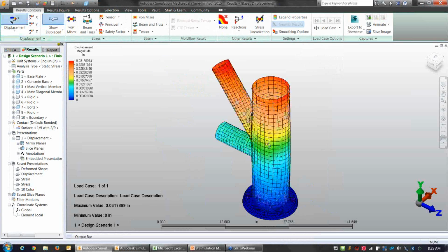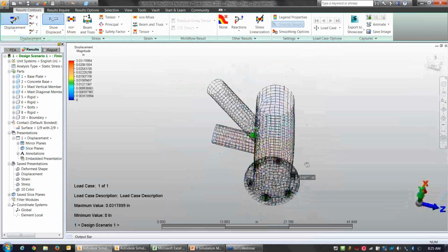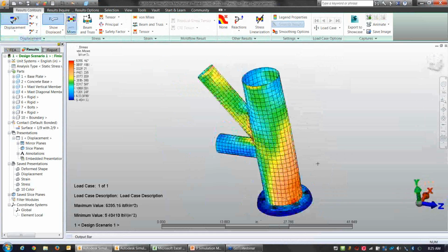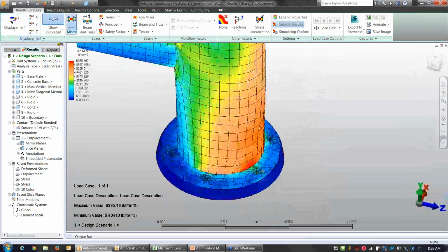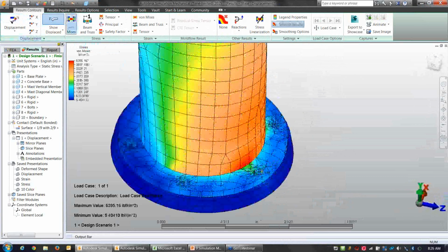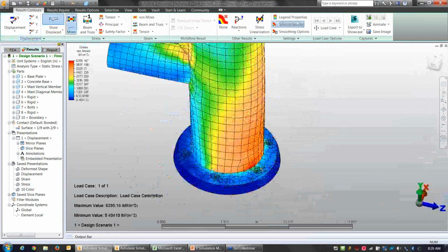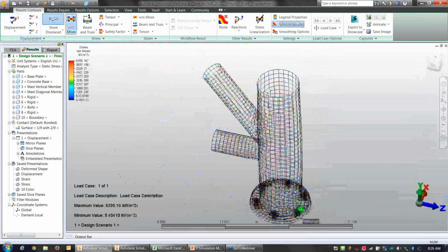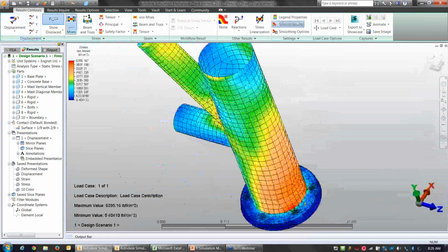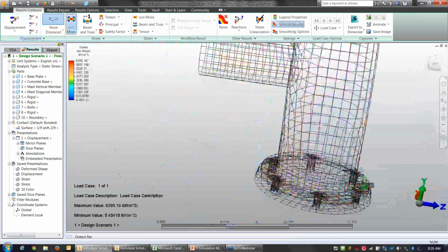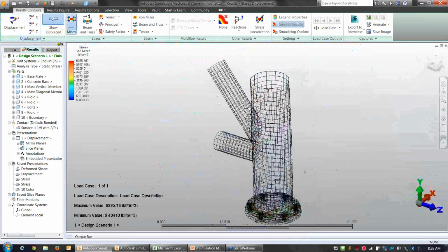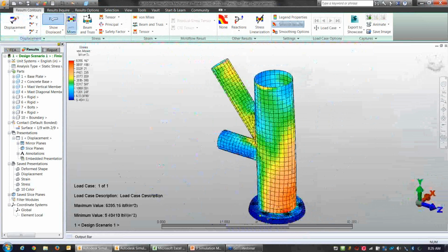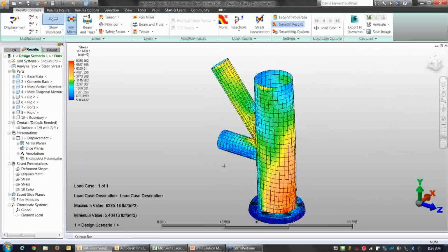Take a look at our displacements. Everything looks pretty good. Von Mises, how are we looking here? Wonderful. Some stresses there. Nothing really to worry about. Everything looks good. Our plate is holding up very well. In fact, probably a little stronger than what it needs to be. Maybe we can go back, do another analysis. Well, I have to remodel this. This is a solid. But we can see the current design appears to hold up.